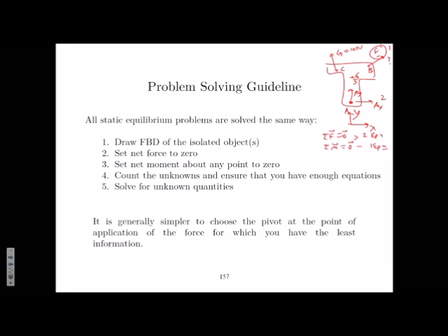For that, I can try to find what the perpendicular is. So I have the line of action of G, I extend it, and then I drop a perpendicular from point A onto this. So using trigonometry and geometry, I could find that. Or if, let's say, I know the angle of G from horizontal, let's say this is theta, then I can resolve G along x direction and y direction and use the component method to solve for the moment of G.